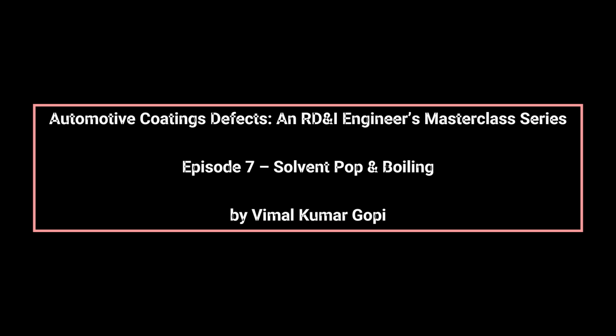Using a fast reducer in high-temperature environments is a classic mistake. Fast solvents evaporate too quickly, accelerating skin formation and sealing in slower components. This creates a high-risk condition where internal pressure builds rapidly during bake. In contrast, a properly balanced solvent blend with adequate mid and slow evaporating components keeps the film open longer, allowing continuous solvent diffusion and pressure release before skin strength becomes too high.